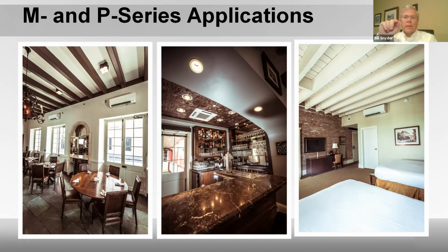Your line set, your electricity, and your condensate will typically go out the back of the wall, and then typically straight down, because condensate water has to go downhill, and you put the condensing unit, or the outdoor section, right outside the wall. But in this case, they must have taken a hard turn and gone around this unit, down the wall. Maybe they have their condensing unit sitting outside of what looks like a fireplace here. Not sure, but you have to consider that.